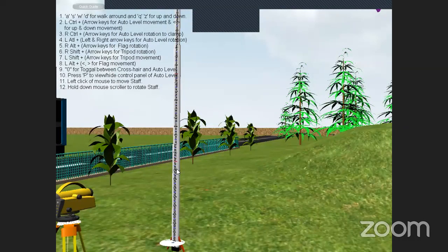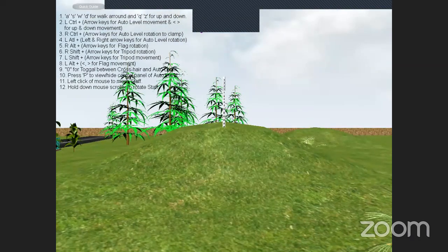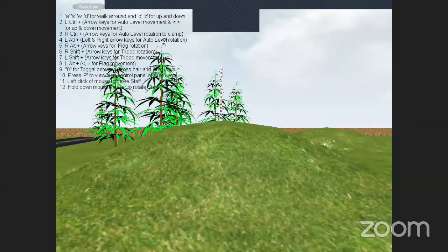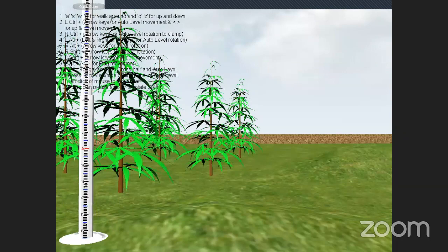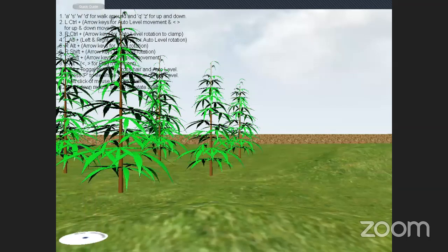Now I am going to observe the D. I am going to move my staff to position D. I don't think it is visible from here. So I have to take again. No, it's not visible. So again, I have to take the back side. I need to take the back side again to the C by shifting the instrument a little bit.